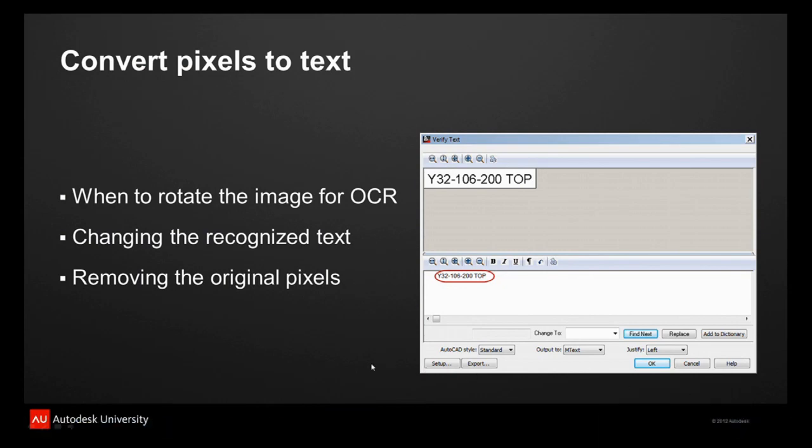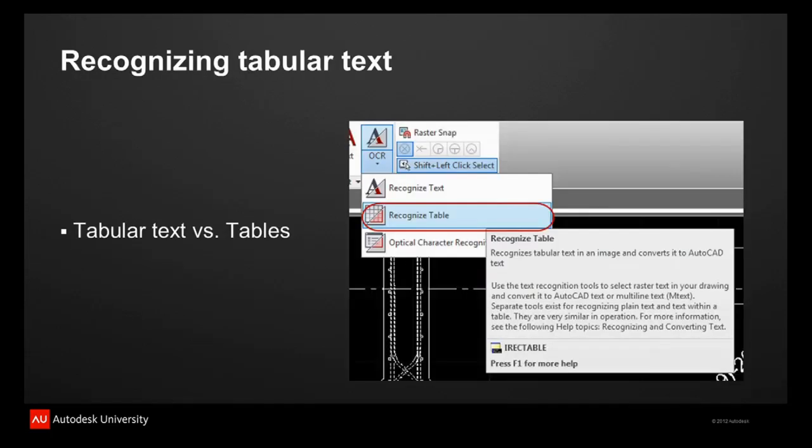All right, so that is basically how the text recognition process works. It's quite simple, it's quite easy to work with. One thing that I have encountered is sometimes when you insert the images and you use the insertion wizard, contradictory to what I said before, sometimes when you use correlation there and you rotate the image by 90 degrees, it doesn't pick it up as a straight line, it actually throws the characters below each other. But that's only happened to me once.